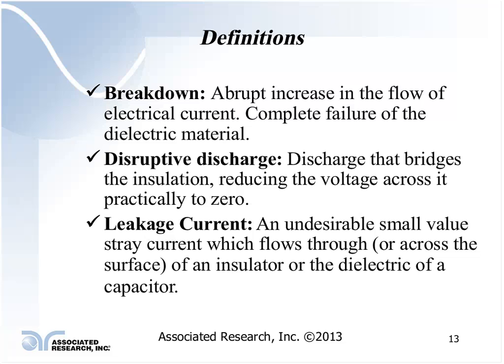Some of the problems that I have seen over my 44 years of experience: some of the safety agencies, when they come in and do your quarterly or semi-annual inspection on your product, are there to verify that you are testing in accordance to the safety standard, and that your product is being manufactured the same as what it was listed under, where they did the agency listing on that product.